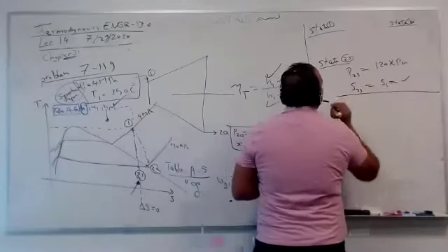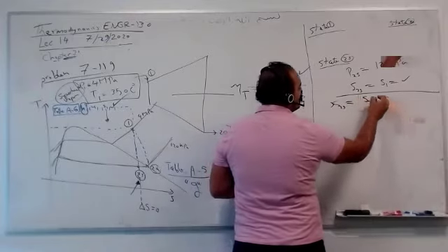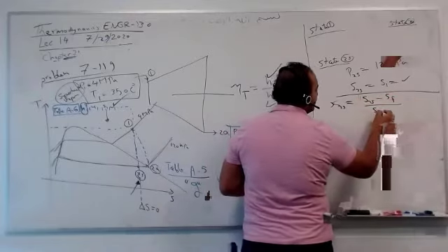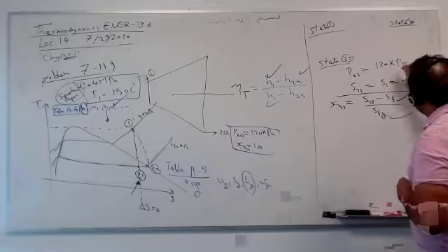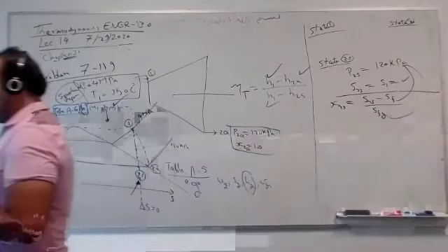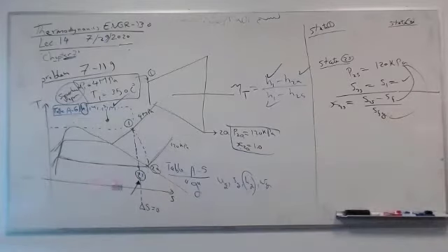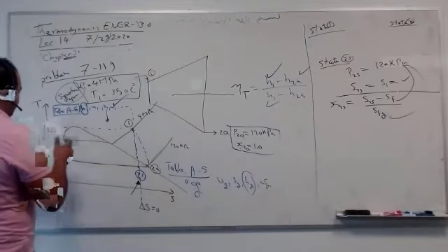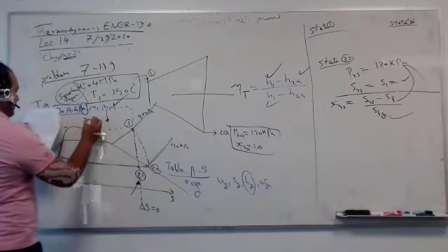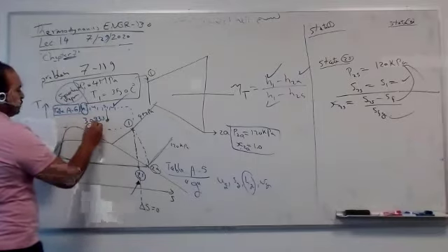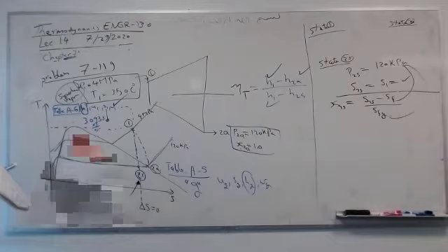2S has the same pressure as 2A. It means X of 2S is equal to S2S minus SF over SFG. So the same information at 120 kilopascal, table A5. If you do that, guys, so let's write numbers. H2A, start with H1, was 309.3 kilojoule per kilogram.